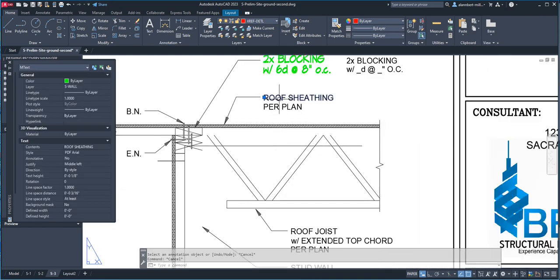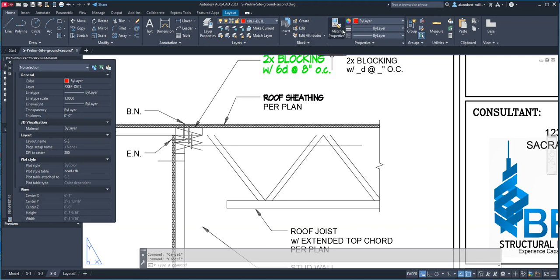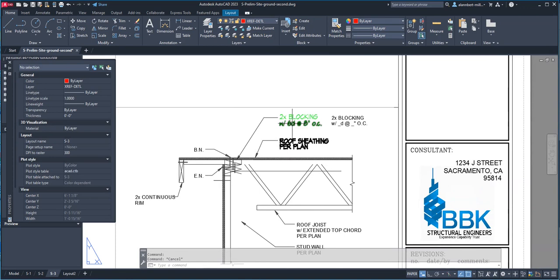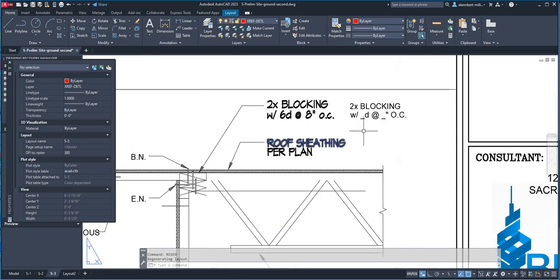or you could find this and assign it an arc 75. Make sure that they're on the same layer. Let's see if I can change this now. There you go. It's now changed. It's in the same layer, S wall, and everything is the same. This one's green until we type in regen. Regen. There you go.